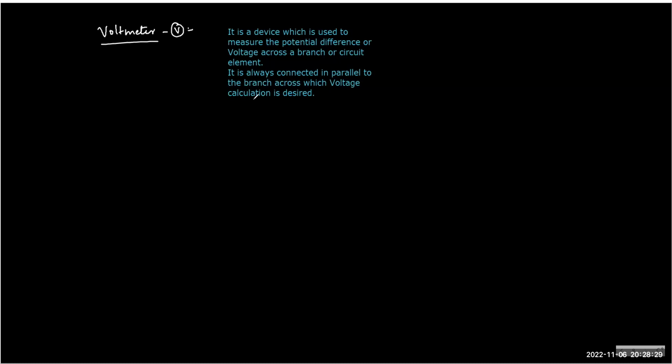So now if you go back to the original galvanometer, this was your device. What is the maximum current it can tolerate? Your original device can tolerate IG current. So across its terminal, what is the maximum potential difference we can achieve? IGRG.